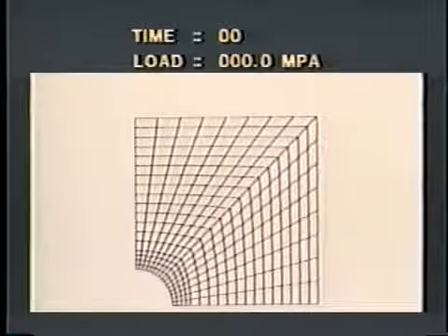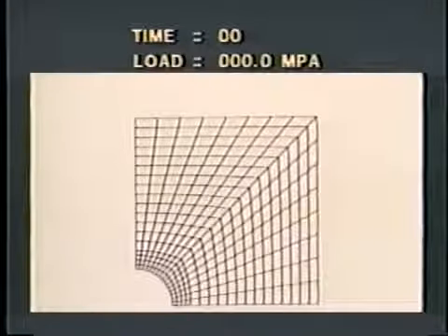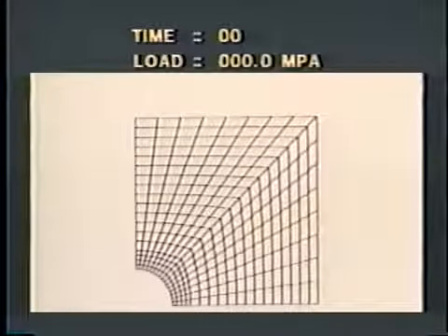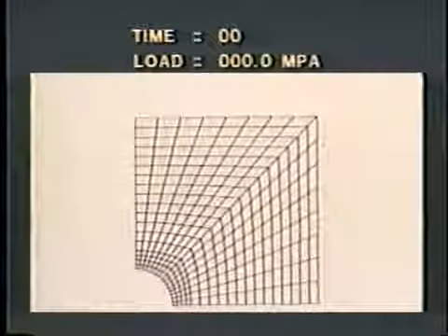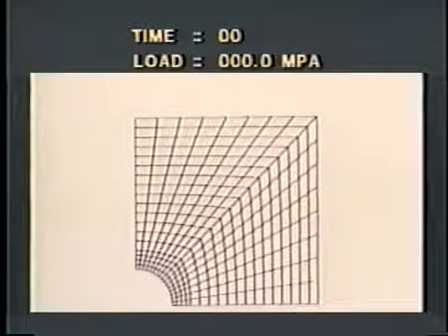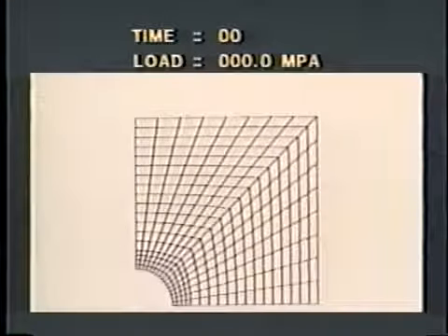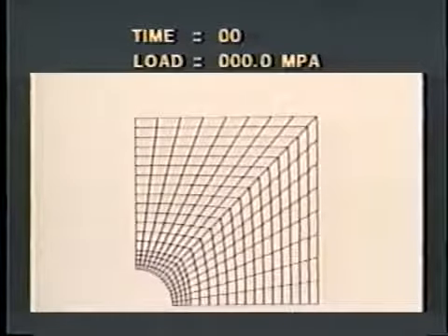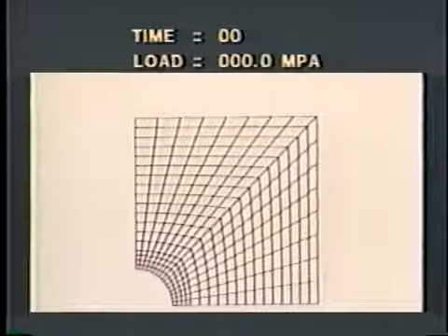The time code given above the plate gives the time of the load step. Also given is the load applied at that time. However, note that we perform a static analysis. Therefore, the time code merely denotes the load level, as we will discuss later in detail. Each time increment of 1 merely corresponds to a load increment of 12.5 megapascal. We will increase the load monotonically. The plate will become plastic at the hole, and this plasticity will then spread until in essence the plate ruptures.